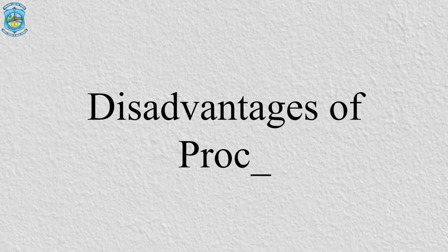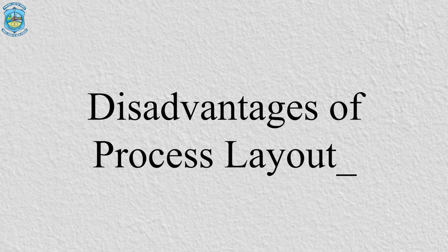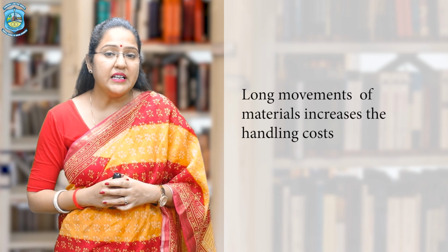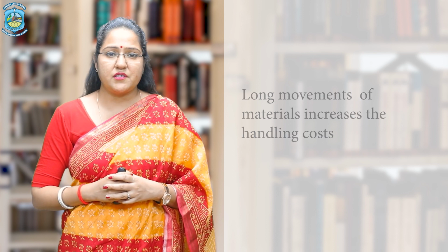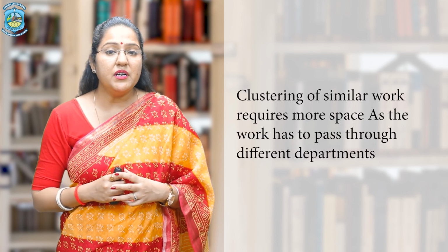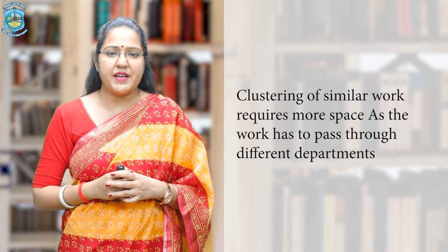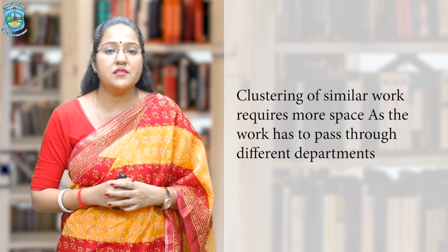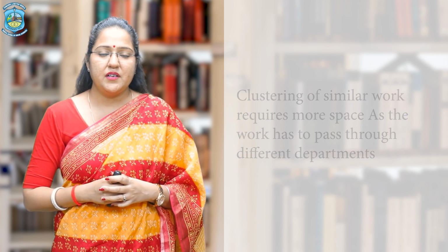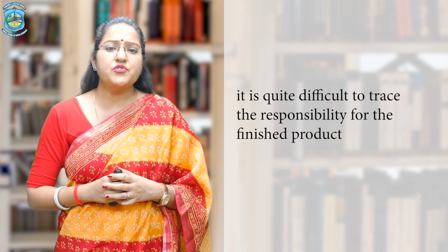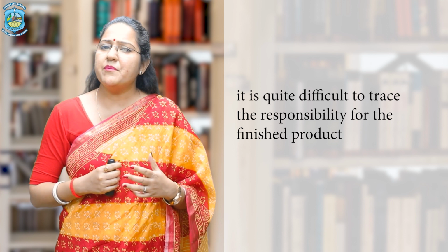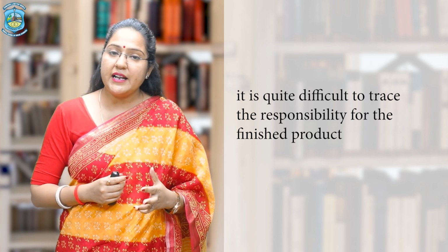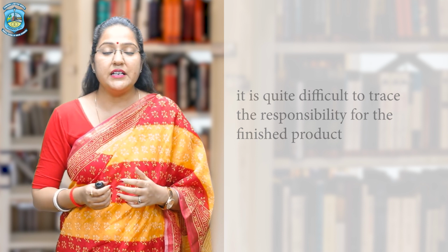Now, let us see the disadvantages. Long movement of material in process layout increases the handling cost. Clustering of similar work requires more space as the work has to pass through the different departments. It is quite difficult to trace the responsibility for the finished products since there are many departments that are interconnected and dependent on each other.